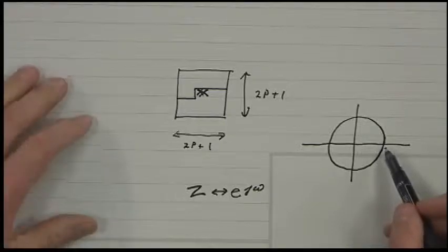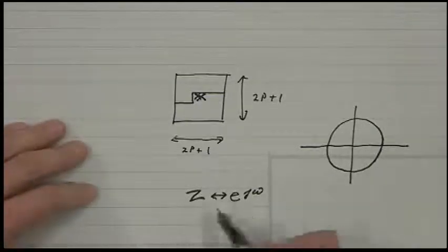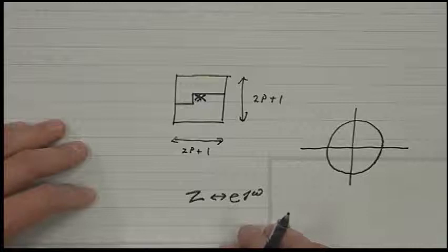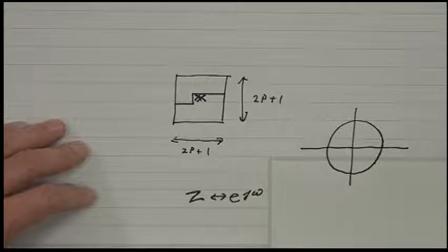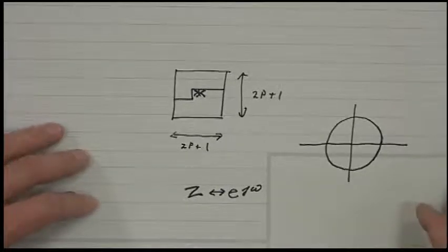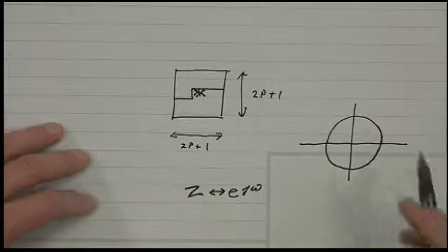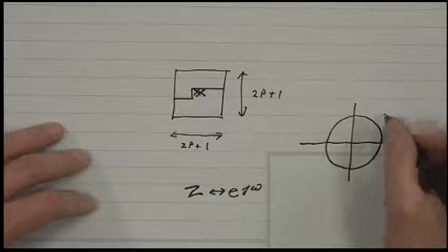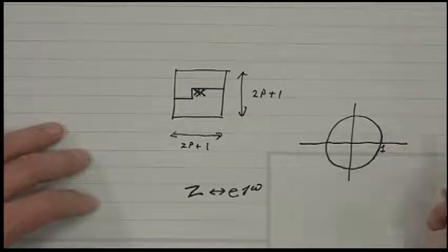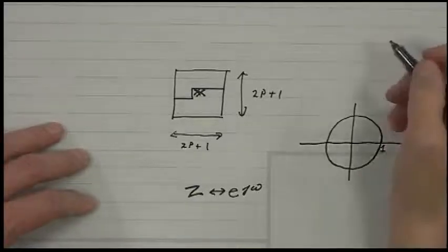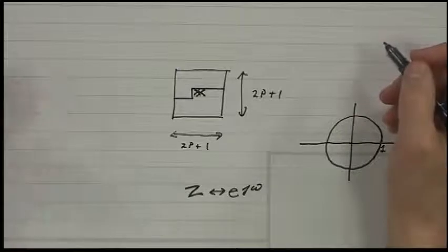But the other way of thinking about it is that it's like shorthand notation for the Z. Basically you just have to make sure that when you're doing things with the DTFT, the expressions you're writing are valid. You can get yourself into trouble if you completely ignore the theory because, like for instance, if this is the unit circle, two different impulse responses can have two different signals.